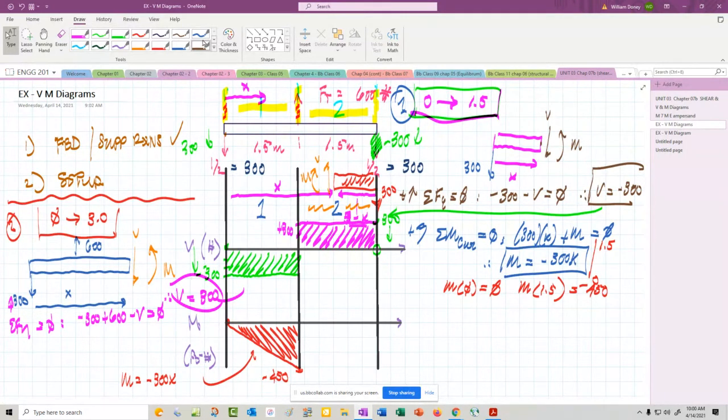Looking at that, we can see that the maximum shear occurs right here. Why do I say it occurs right there? Because right there, there's a difference of 600 pounds, a change of 600 pounds. It goes from negative to positive. So if we're concerned about this shearing off, that's where we'd expect it to possibly happen first, assuming the beam was continuous in materials and setup and it was the same all the way across. We would be concerned about that. So we use 600 as the maximum shear.